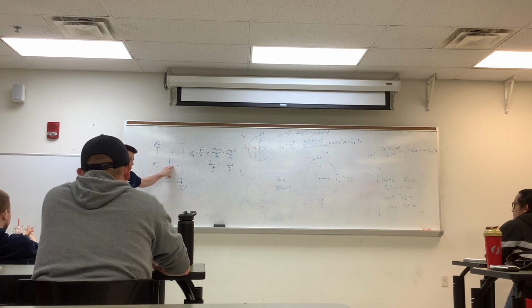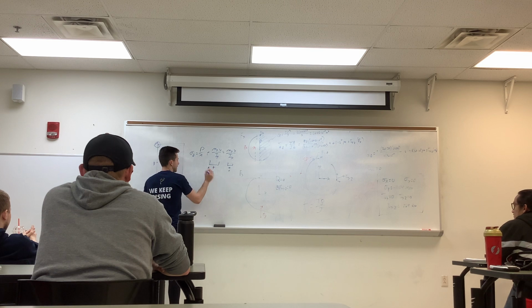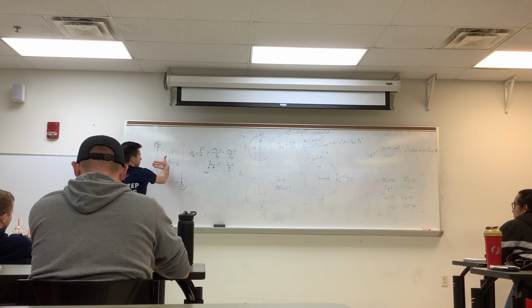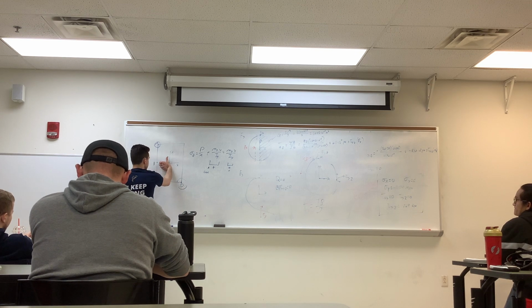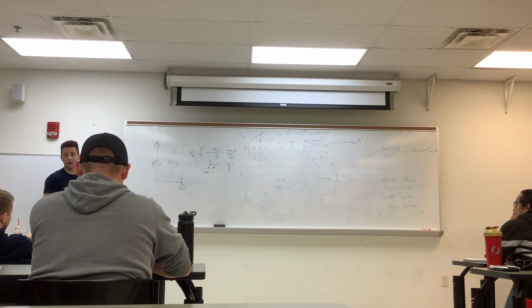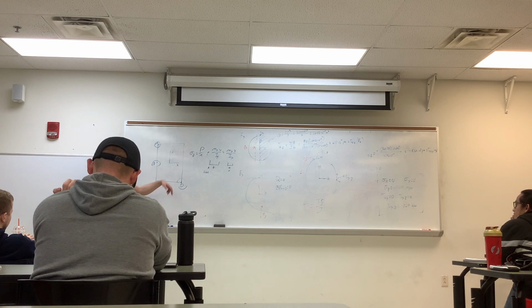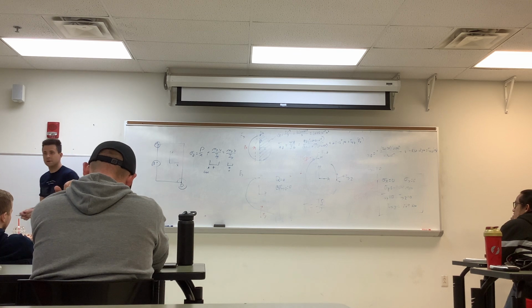So what you put your thumb along, that'd be your positive x-axis here, and then this is where your fingers curl, if you're using the right hand. So for the next one, the positive axis, positive y, I'm going about the y. Oh, I see. Curl your fingers, and then you get it at both points, B and A. It'll be in tension coming out of the page here, but at point D it's compression. So you lay your thumb on the positive axis.